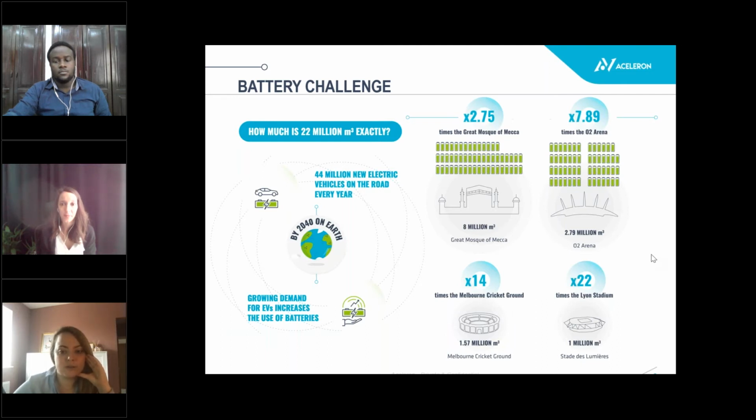The lithium ion does have many benefits over these lead acid batteries. So they're typically more lightweight, often up to 1/3 of the weight for the same capacity available. And the lifetimes are far better, meaning less interrupted supply. And it can also reduce the total cost of ownership for the owner.